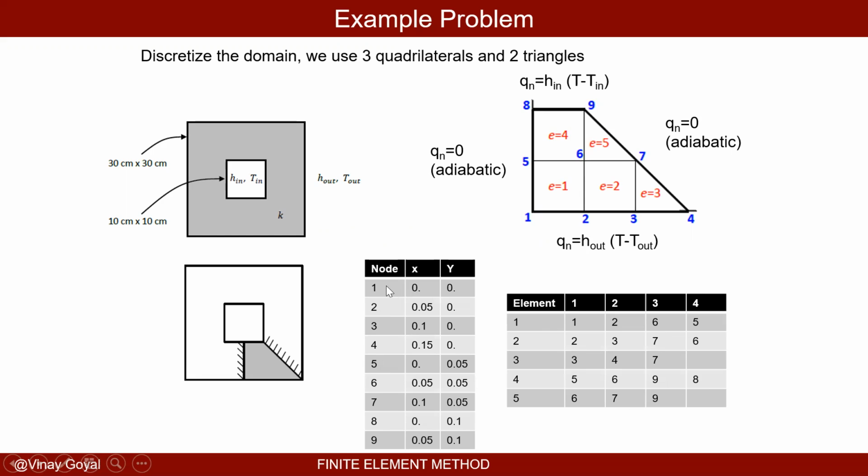Now I can also plug in here the nodes, the X and Y coordinates. X, I have, the nodes 1, 2, 3, 4, 5, 6, 7, 8, 9. So I know the nodal locations. So I can just put the values here. Simply put it there. And I convert it from centimeters to meters. And I invite you to check it at home in the comfort of your home so you can see that you get that these are the coordinates for those nodes.